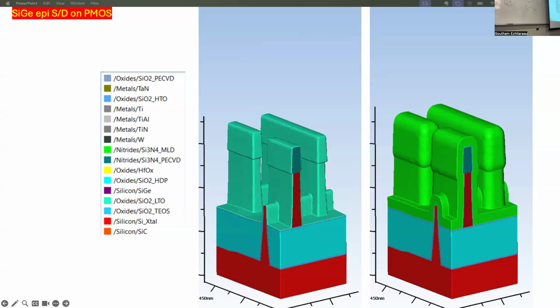Yeah. How do you do the sidewall spacer over the fin? Oh, no, we're not doing it over the fin. Remember, that's a slightly confusing thing here. In this case, the fin is going in one direction, the gate is going the other direction, right? The sidewall spacer is created on the gate. The fin sidewall spacer that we created before was to define the fin, but now we are going to create another sidewall spacer, but it's going to be on the polysilicon gate.